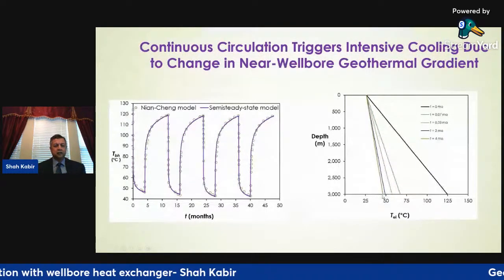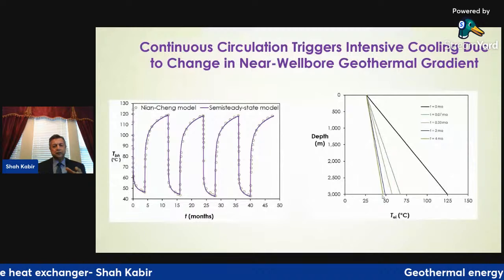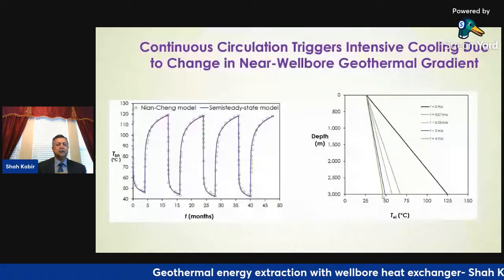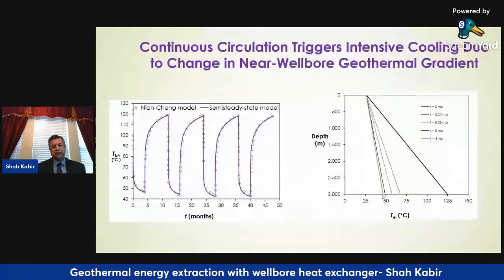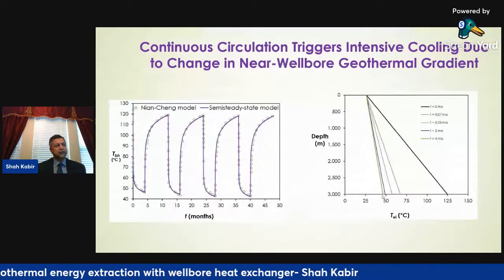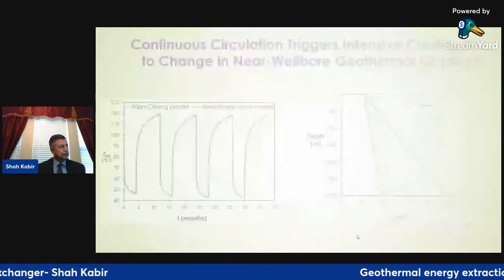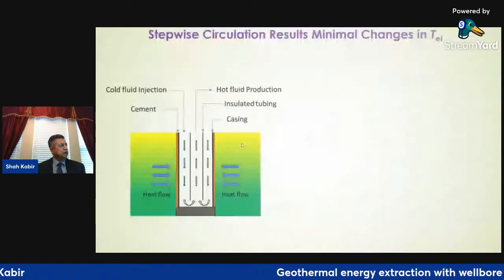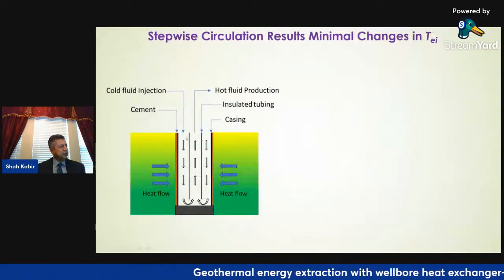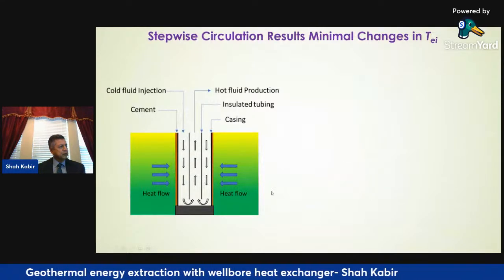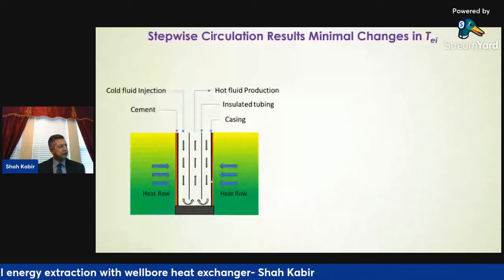Because despite the circulation, the heat transfer that needs to occur from the formation into the wellbore begins to deteriorate seriously. So that's the real reason for that. So what's the remedy? How can we fix it? So again, we are circulating down the annulus and up the tubing in a closed loop system. So the heat flow cannot keep up if you keep circulating.